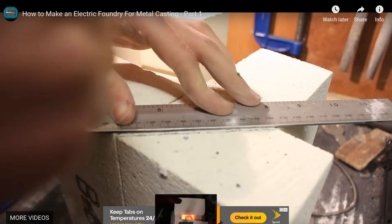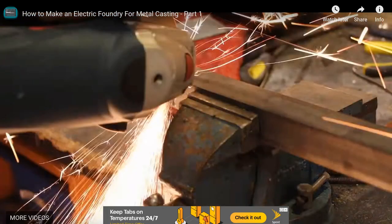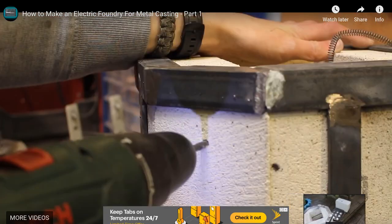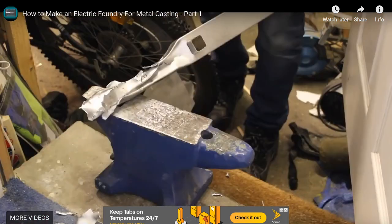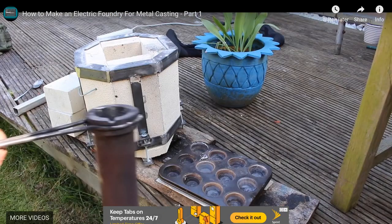Fire brick is not exactly that cheap. You can also use refractory material that you can cast your insulating material and then put the nichrome wire inside of it. The advantage of using a ceramic insulation is that you can put the nichrome wire right into it. It's insulating. So if you made some structures to hang your wire in there, you can do that.